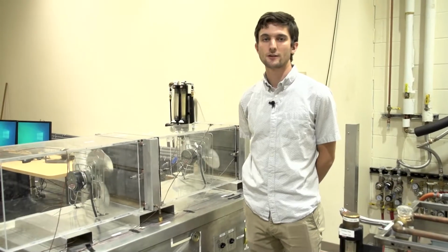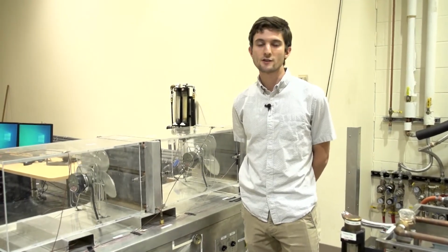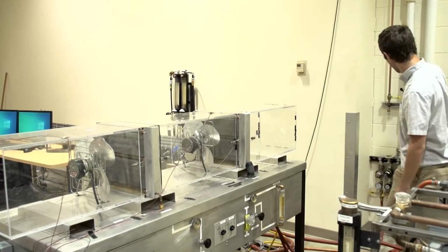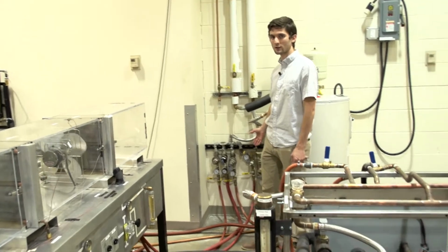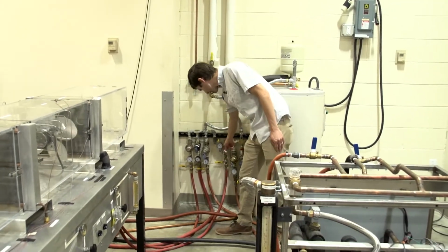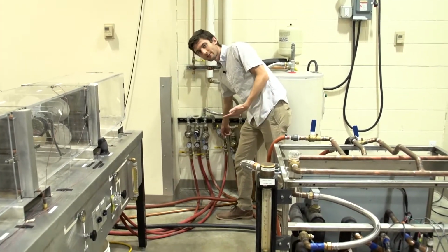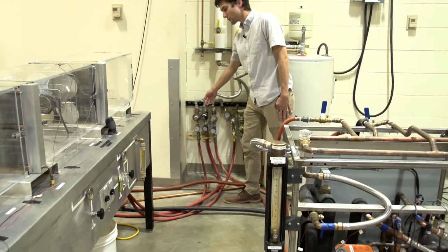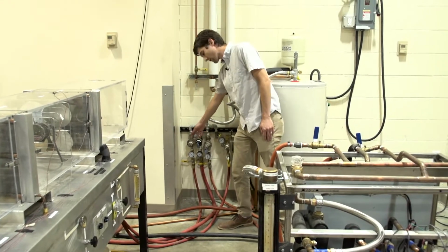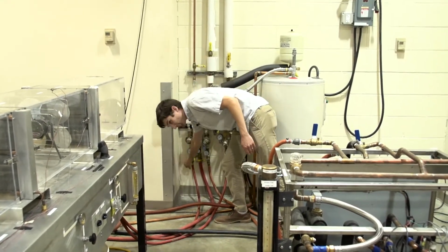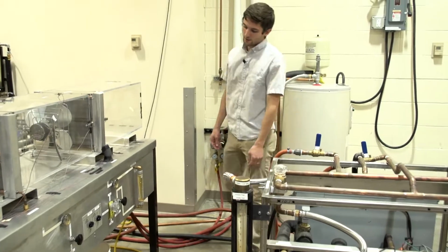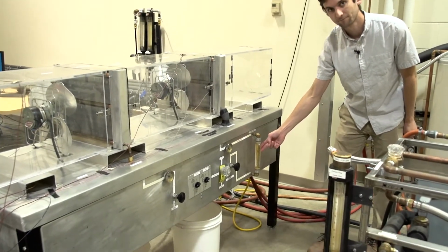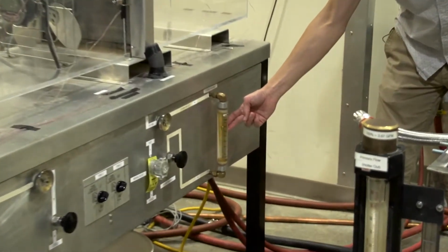Now I'll talk about how to start up and shut down the system. So first, at the wall here, you have the hot water manifold. For the Crossflow heat exchanger, you would just turn that flow on. And then you have the cold water manifold. For the Crossflow heat exchanger, turn that water on. And then immediately you have visual confirmation that there is flow through the system at this rotometer here.